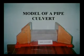You can also see some walls here which are inclined, is it not? These walls are called the wing walls. Sometimes in the place of wing walls we also have slopes. In a similar way we can substitute the wing wall with a slope. That means we provide slopes here filled with granular material, and these are overlain by a thin layer of stone masonry. Just have a look at the next slide.